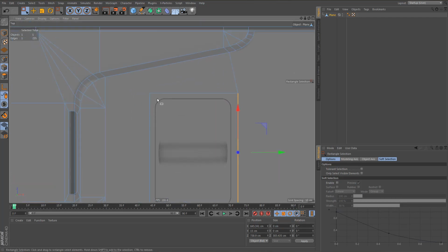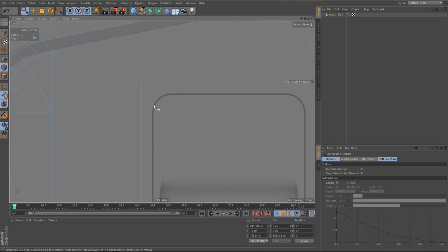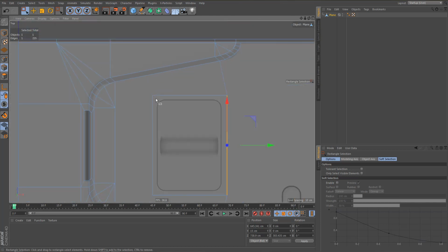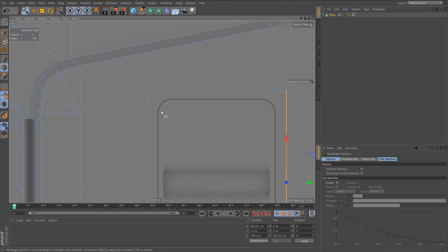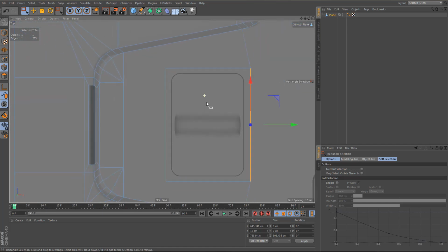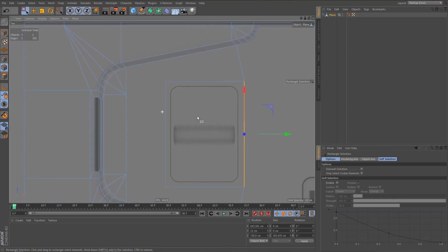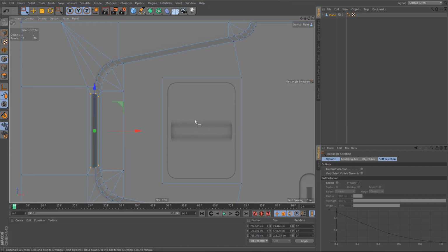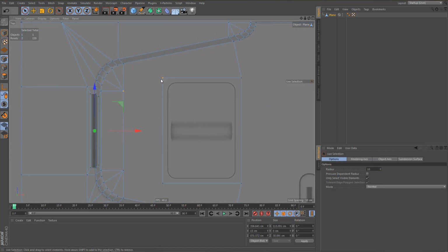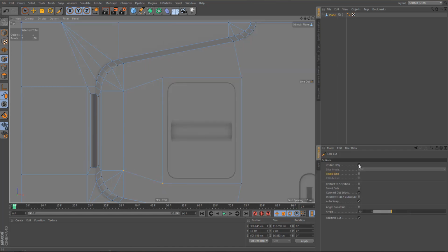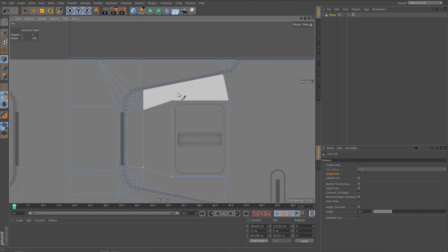And the reason is because these round corners here will create some geometry, and I don't want this geometry to propagate into the rest of the mesh. So we're going to have all of the edges coming from this area and on the corner points of this outline I created around this detail. And let's also clean up the mesh a little bit by connecting these points and by adding some more cuts.